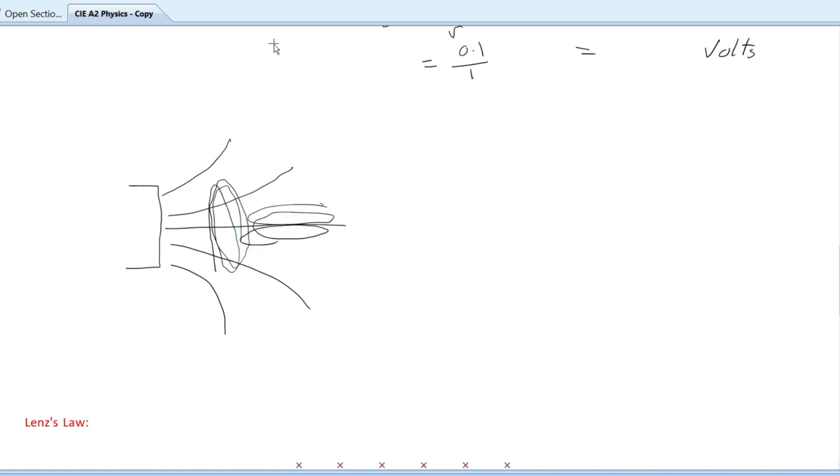If you rotate this coil from a vertical orientation to a horizontal orientation, now you would have no linkage whatsoever when the field is parallel to the area of the coil. No cutting, or the field lines do not pass perpendicular to the cross-sectional area of the coil, so no flux linkage. So here, at first, for example, we'll use the same values.